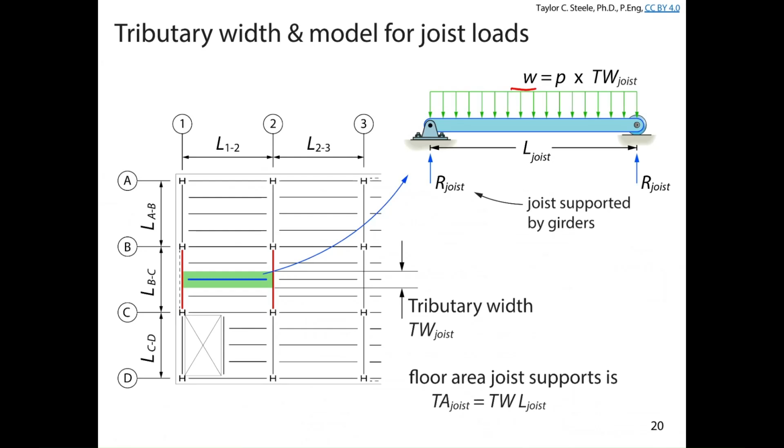Well, W comes from the geometry of the framing, and it primarily comes from the actual magnitude of the loads acting on the floor system. And so if you think about this room, for example, the floor has some kind of subfloor. There's probably a concrete slab that sits on a steel deck that sits on some joists. And then there's a bunch of people and desks and furniture. And there's stuff supported from the floor below it, maybe some ducting, some tiles, some lighting. We'll talk about that on Friday this week. But it's essentially a distributed load of sorts. I know I'm standing here. I'm essentially a point load of X 100 pounds sitting on this one point.